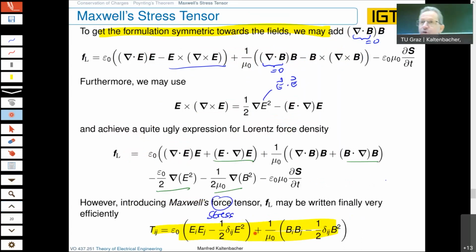Now, if you have an electrostatic field, for example, which is very interesting in MEMS devices, where you make MEMS actuators, then you will have just this term. If you have any magnetostatic or even magnetodynamic actuator, but the time change is in a range that we can still model this with the eddy current case, and we don't need also the wave part, so full Maxwell, then this will be just the part you will evaluate. And it is done in commercial as well as research finite element programs.